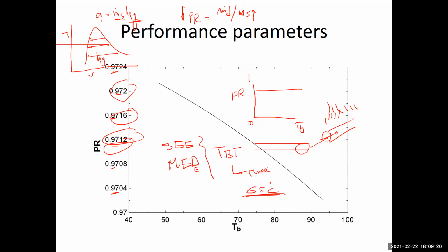But for the single effect or the multi-effect, this is not the case. Spraying is going to be outside the tubes. And to avoid scaling problems, although we use additives like anti-foaming, anti-scalant, and anti-fouling components, still, if scaling starts to occur outside the tubes, that's an additional layer of insulation, which is going to reduce the heat transfer rate. You're not going to generate the same quantity of vapor if you have a layer of insulation on the outside surface of the tube, and the whole performance of the unit would be affected.